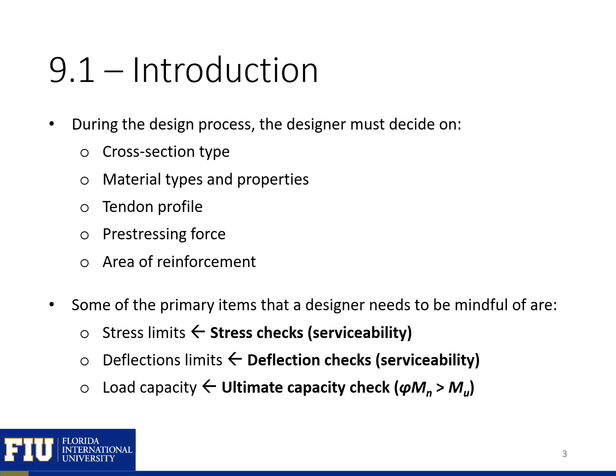During the design process, the designer must choose a cross-section type, material types and properties, tendon profiles, the prestressing force and total amount of prestressing, and also the area of our non-prestressed reinforcement. So, design compared to analysis.